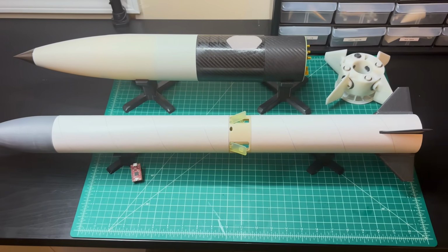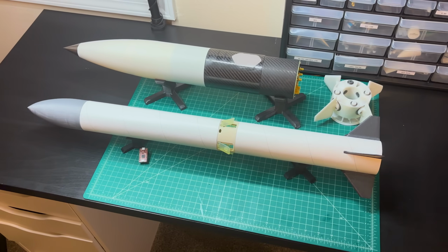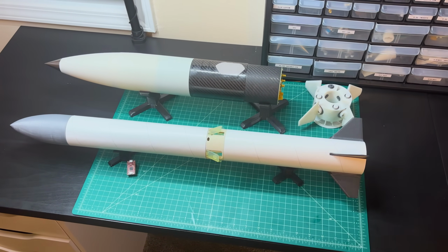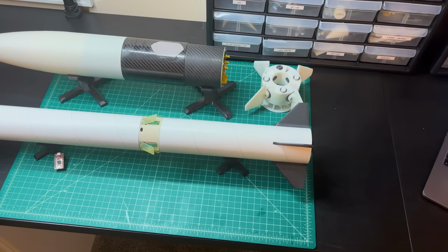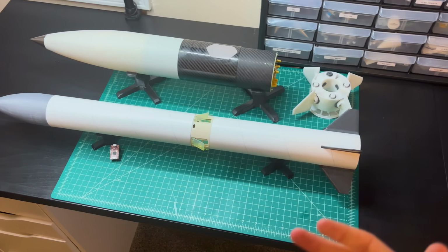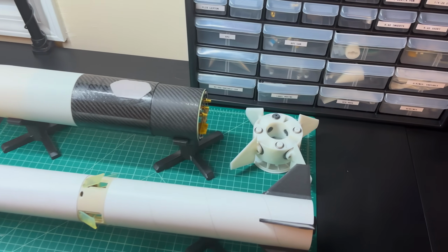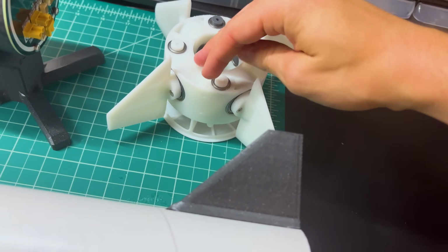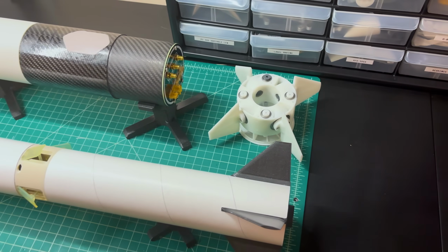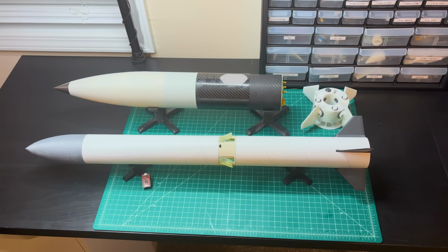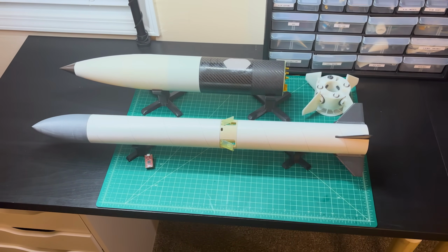The second reason to use modeling and simulation is something called sensitivity analysis. Sensitivity analysis basically answers the question, if you change some little part of your rocket, how much does it change the overall behavior of the flight? If you make your fins 1 millimeter shorter, what happens to the rocket? For some rockets, it does basically nothing. For other rockets, it'll make them unstable. For guidance and control systems, that's very important. Things like, if I have a tiny bit of backlash on my control surfaces, how much does that affect my rocket flight? Sensitivity analysis is something that we'll explore today, and it's a very important part of your rocket designs, especially as you start making them more complex.